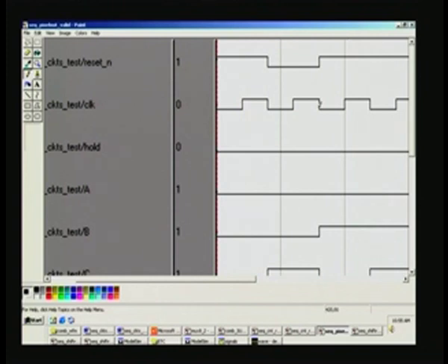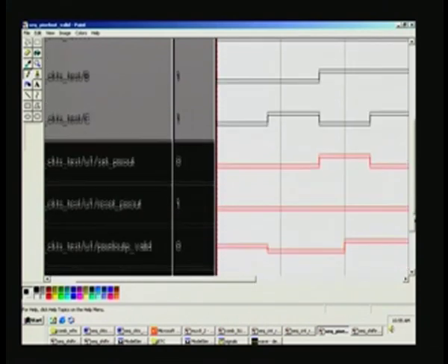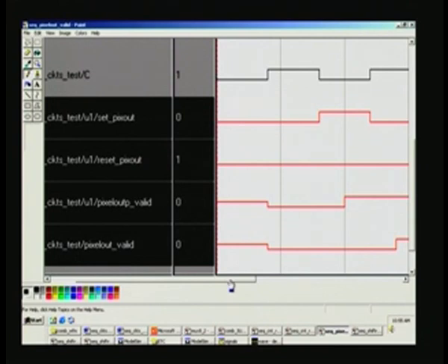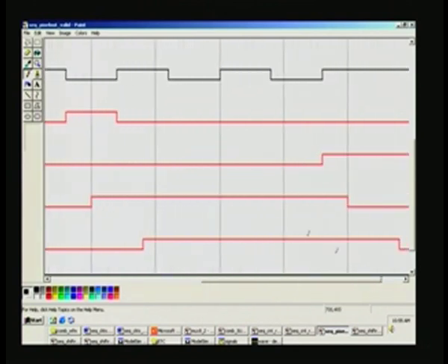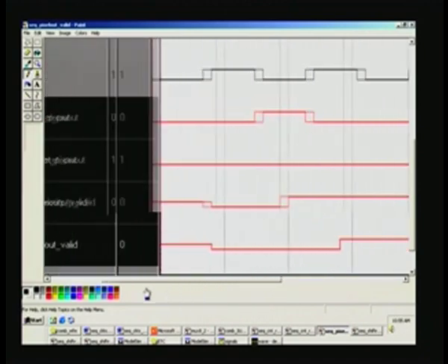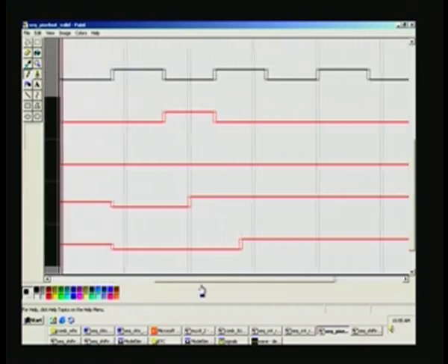So, now this is in synchronous mode. Any register will always be a synchronous type and it will happen only during the positive clock edge transition, and that is how you have set the pixel out P here, and we have also a reset here and that condition is satisfied and it remains high here, and after a delay you are getting here the final output, and it is going low here because this has gone high. This is the reset pixel out, right.